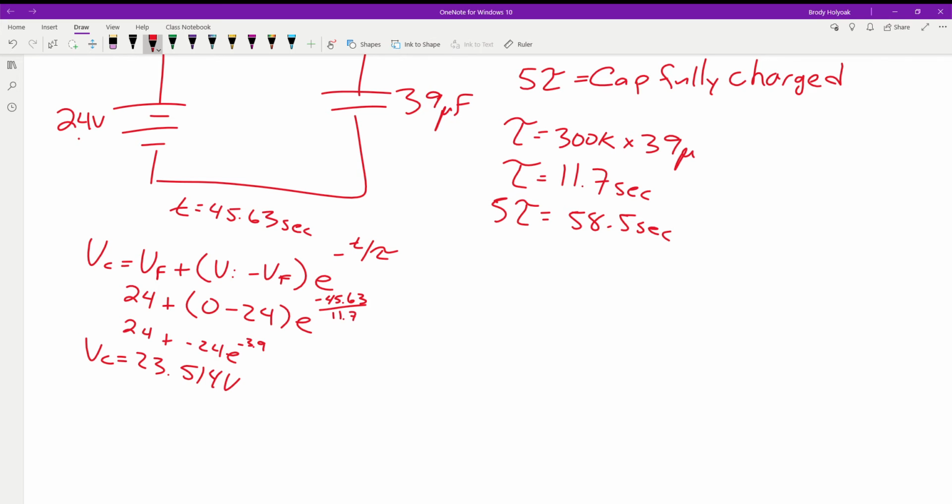So even then, we could take the 24 times the 98.3, and we're at 23.592 as if we went to the full 4 tau, which we're just barely under. So the answer makes sense as far as our ratios. And that is what our question is asking us.